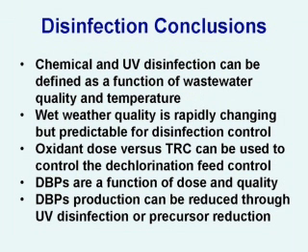This shows dose, and dose normalized by COD and temperature, as compared to HAAs that are produced. So this is the disinfection byproduct. If that's a concern in the receiving water, then you want to be concerned about how you remove particles before you disinfect in that stream.